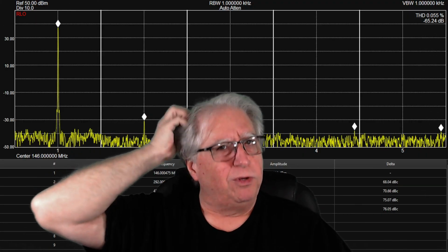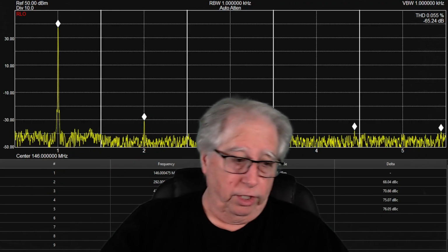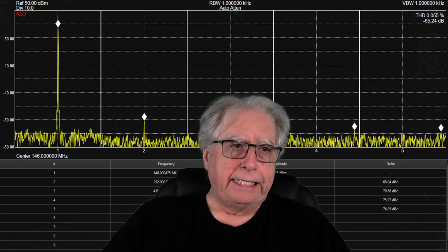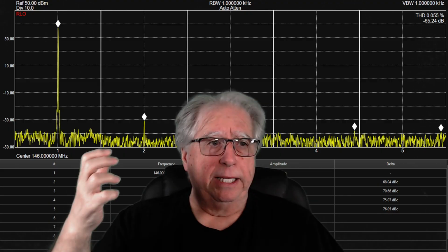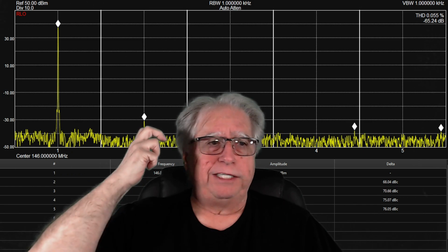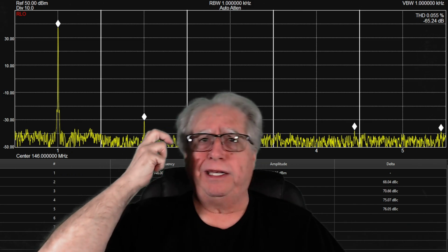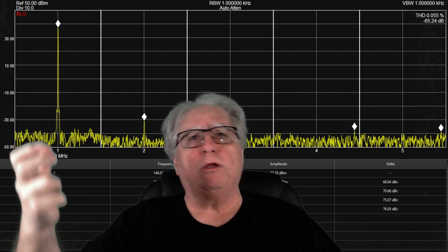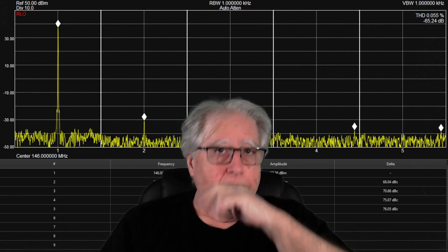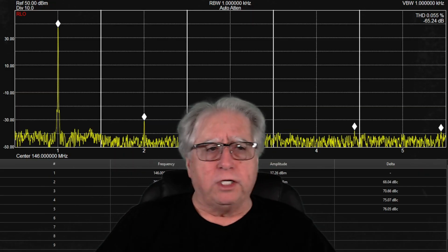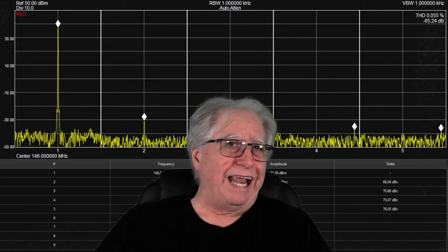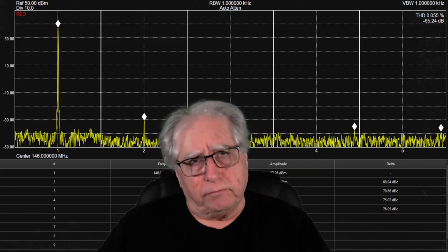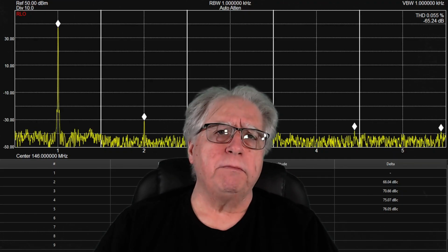Okay, I've got a communications problem here. Could it be a bad antenna? Sure. Would I be able to pick up, on an HT sitting next to the radio, it transmitting? Absolutely, I'd be able to hear it, right? I'd be able to hear its quality. Doesn't mean that's the quality that's going out the antenna. So keep that stuff in mind.